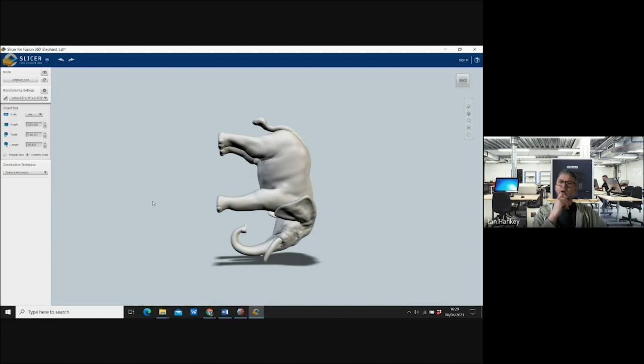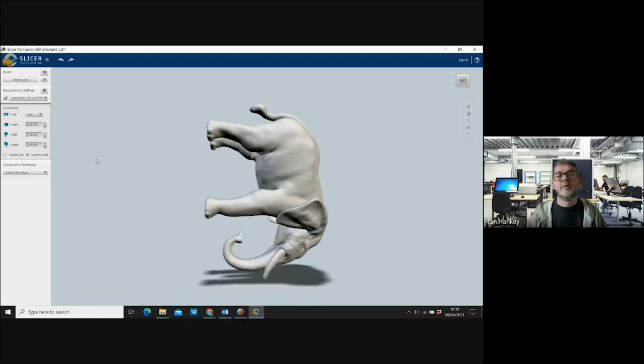So perhaps I'll use an elephant on a half of my sheet, and they've got 4. So perhaps, yeah, I'm going to go for round about 250, just under 250 height. I'm going to make it 245. And the reason for that is I don't want to go right to the edge of my wood, because sometimes it's worth keeping within the boundary of our material, within, say, 5 millimeters all the way around. So maybe 245. I can always change that later. So my elephant is now a little bit bigger.